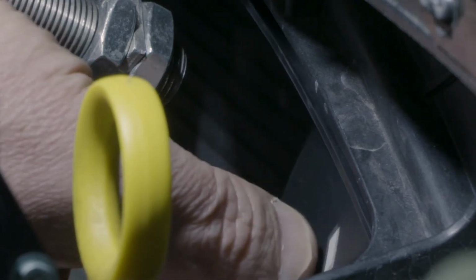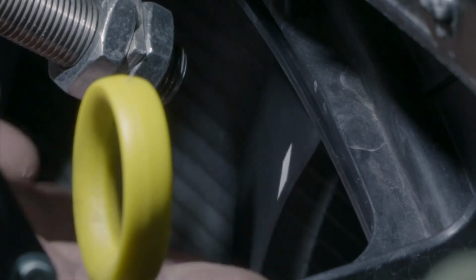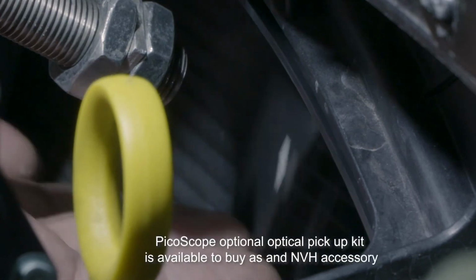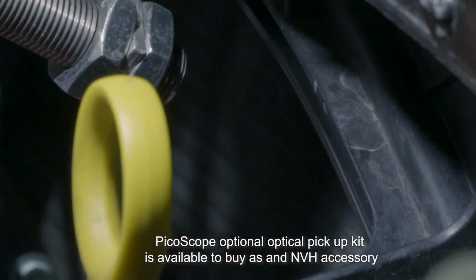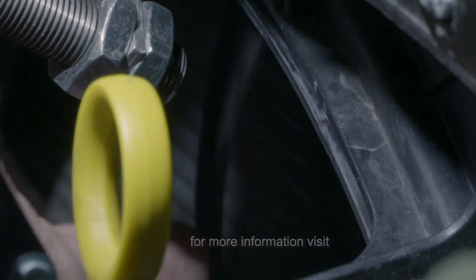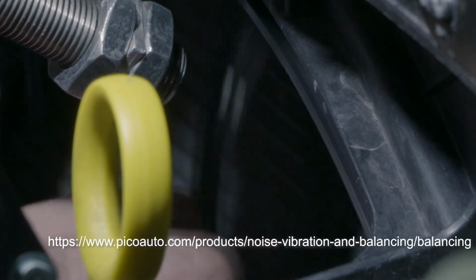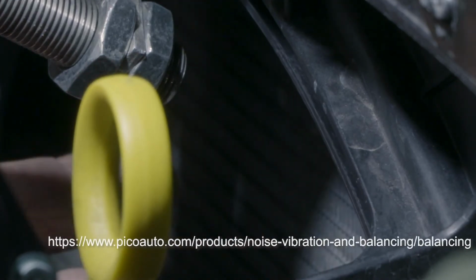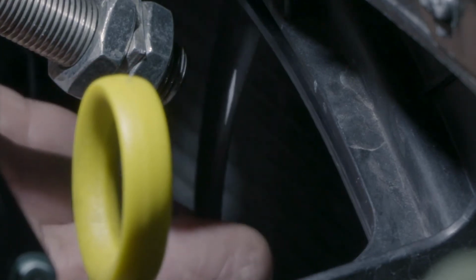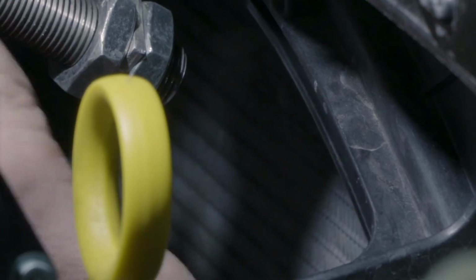We attach some silver tape here and point the optical pickup at the cooling fan. So every time the silver tape passes the optical pickup, it generates one pulse per revolution. That will give us the frequency of the fan. We can then use PicoScope to not only count those pulses but display the frequency of those pulses, which should come out around about 36 hertz, because that's where we captured our peak amplitude vibration, at 36 hertz in NVH.